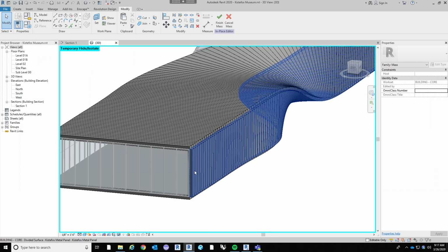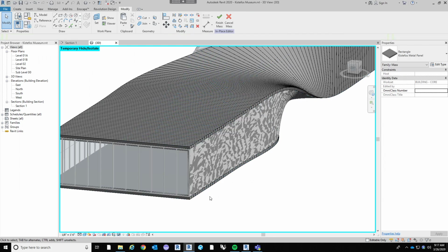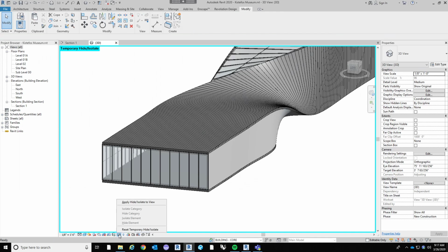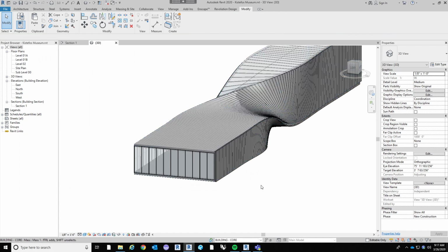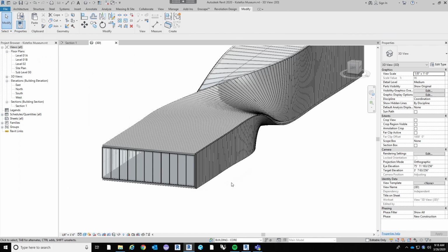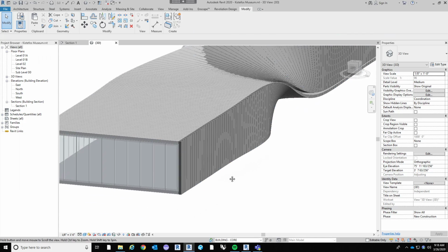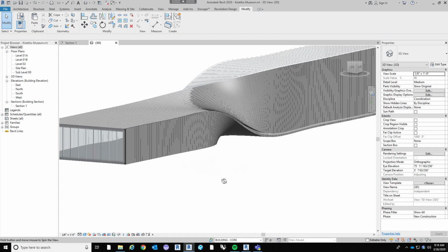So I'm editing the original mask that had the weird corner. I'm going in and deleting the side panel. So now that is empty. Finish the mask, reset the profile, and now we have a nice clean corner with the metal panel on the side going up and capturing the one at the top.